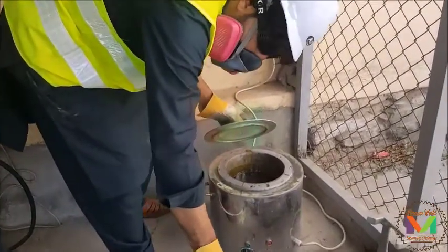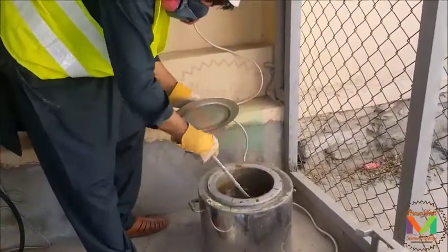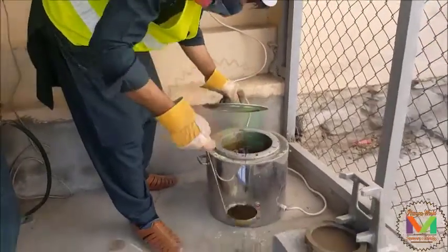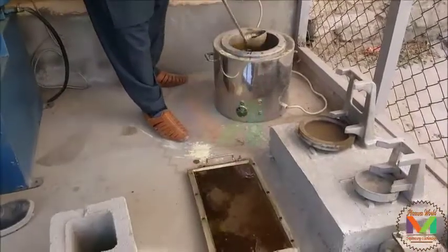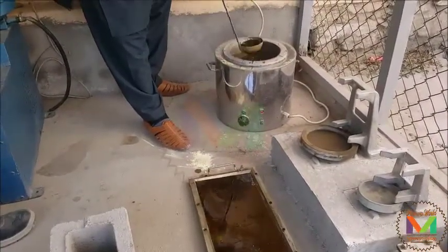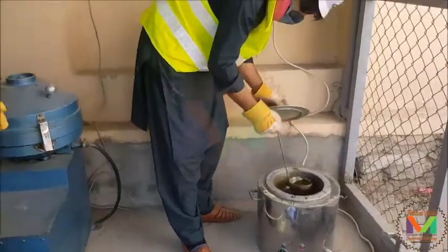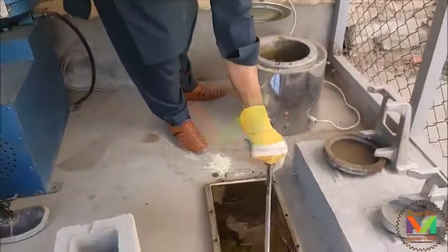Form a rectangular mold on the capping plate whose dimensions are approximately 13 mm greater than the overall dimension of the specimen. The mold must be sufficiently rigid not to move or deflect during the capping operation, capped in the sulfur capping material without overflow.